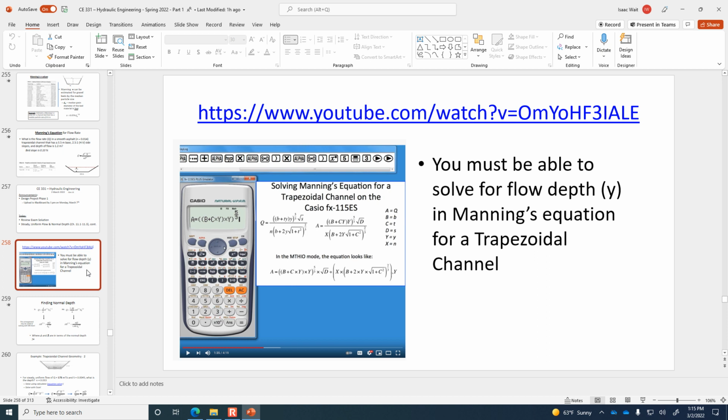You can do a vertical slope with concrete or rock, but if you're excavating into clay and sending water down that stream, it's not going to be long before it slumps into the channel and sets itself up into something approximating a trapezoidal shape. So trapezoidal shapes are really common for engineered structures, but they also naturally set up when you've got a soil that only has enough cohesive forces to stay together at a certain angle.